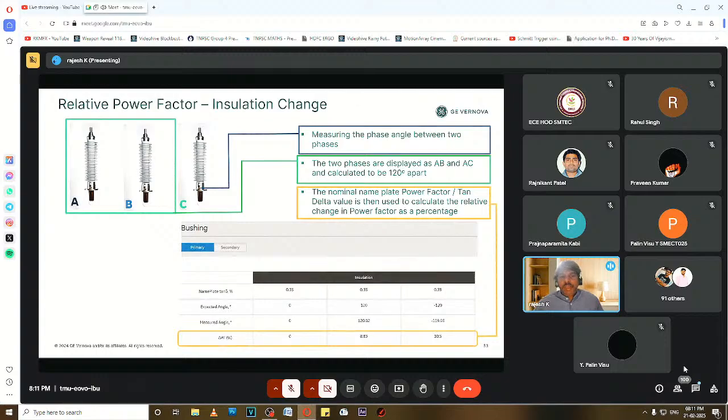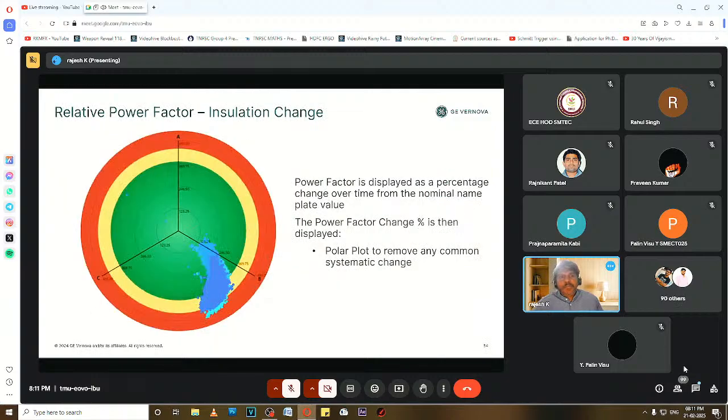So this shows if there is any change, it will give an alarm, and you can always see how the interface is, phase to ground how it is, phase to phase how it is. So the sensor will always provide detailed information in a live format, like how it is shown here. Okay, so it will give full information about the percentage of the tan delta over a period of time. So this shows how the relative power factor percentage, or you can say the tan delta power factor, delta power factor has changed. If there is any relative change happening, it will give an alarm, and it will also give the healthiness of the system over a period of time, or maybe because of the load if it is happening. So you will have a clear picture since the data is all recorded and in the trend in your system. It is always available for your diagnostics.